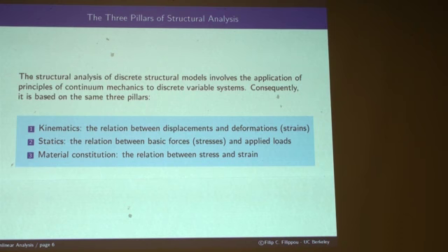All right. The first point I wanted to make as we go through this introduction is my insistence that we appreciate that, exactly as continuum mechanics teaches, and I hope you were subjected to those kinds of courses rather than formulas that one can copy, the whole edifice of continuum mechanics is based on 3 pillars. First pillar is called kinematics, and is a relation between the strains and the displacements. The second pillar is called statics, and is the relation between stresses and forces, forces of the element, of boundaries, or whatever. And the third pillar is, of course, the material constitution, which is the relation between stresses and strains. These are 3 independent pillars.